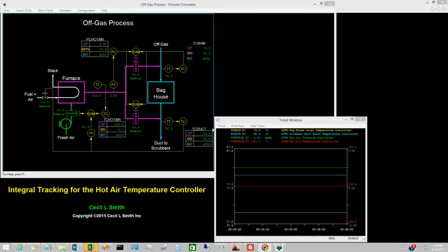For a PID controller to perform as expected, changes in the controller output must lead to changes in the opening of one or more final control elements, which must affect the measured variable for the PID controller. Driving a final control element to either limit disrupts this sequence.